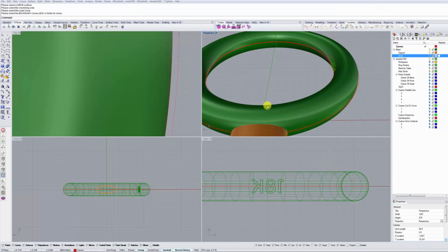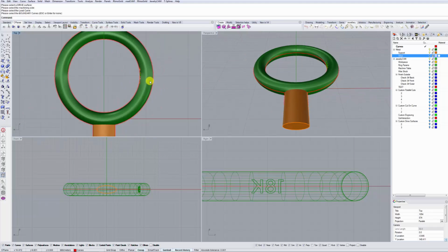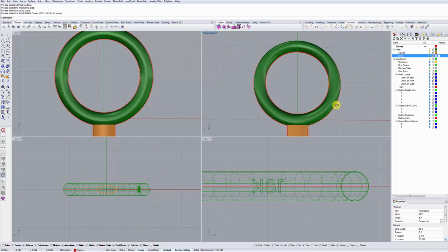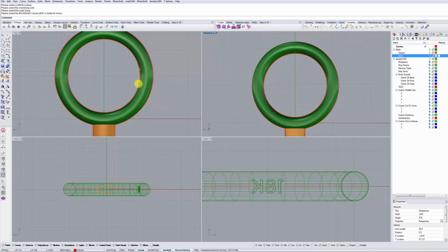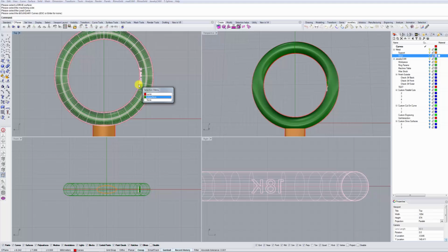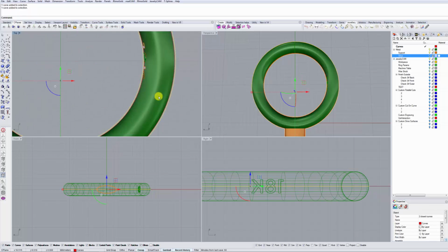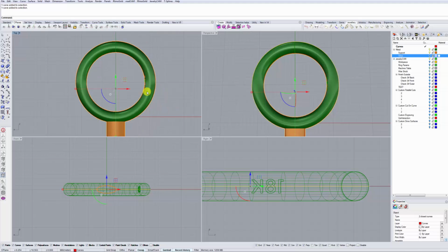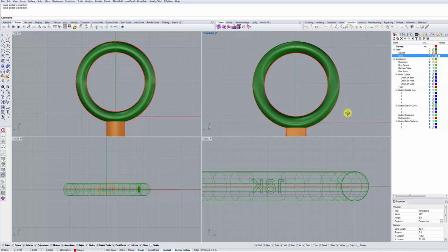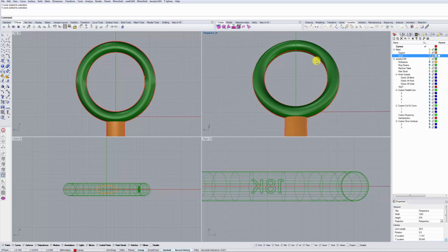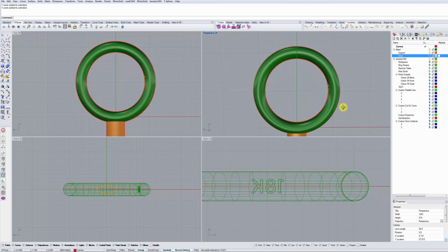So now let's look at a different way of cutting the same ring using a different strategy called drive surfaces. Drive surfaces are basically a different way of specifying boundaries which the mill should follow when cutting your ring. And the big difference is that while our curves, of course, are only two-dimensional, in the sense that they can only specify boundaries in 2D, our drive surfaces can be 3 dimensions, not just specifying an area but also an angle. But of course they can also be 2D as well, and that in itself has some advantages.